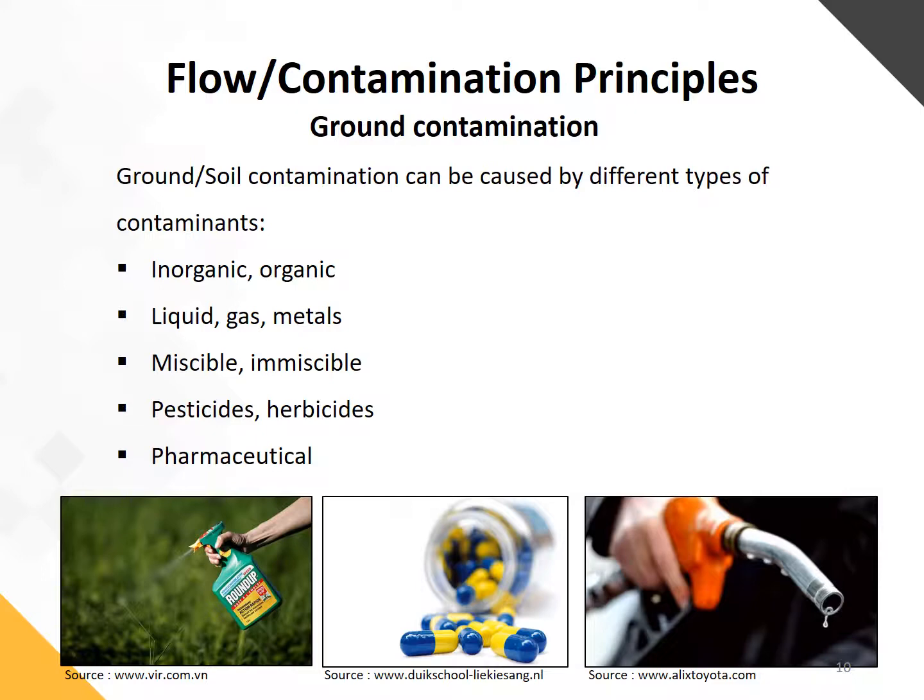Organic contaminants are often found on agricultural land. When the farmland is extensive, the soil becomes saturated and the excess water starts to flow when it rains, contaminating the surrounding waters. They are generally toxic to the fauna and flora of the soil. In addition, they can cause acceleration or eutrophication of water bodies. Eutrophication is the excessive buildup of nutrients in the water, which causes a dense growth of plant life. In other words, it accelerates the process whereby a lake becomes a swamp.